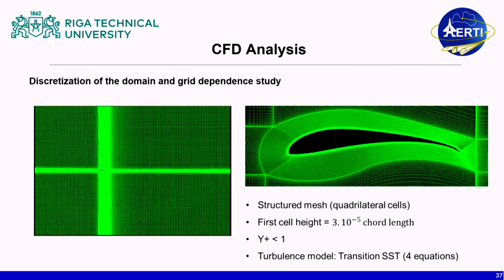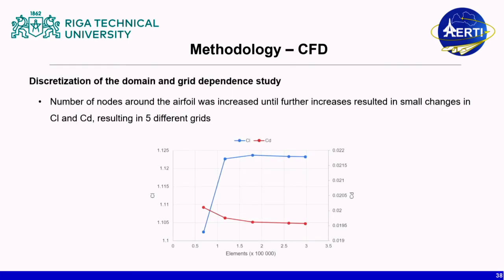Okay, the CFD analysis, this is the second level of verification of our results. For the understanding of the flow mechanism and the viscosity effects in the aerofoil, which were absent in X-foil, we did a further tier of analysis. So a computational fluid dynamics analysis was performed. We created the mesh in ANSYS ICEM, and we used ANSYS CFX and ANSYS Fluent for the simulations. I will not go into much detail, but a mesh independence study was also performed, so the results are independent of the number of elements we used for the meshing.